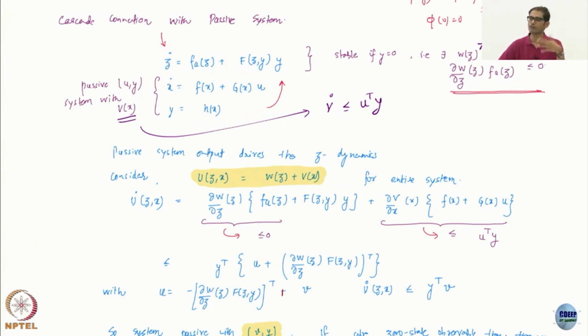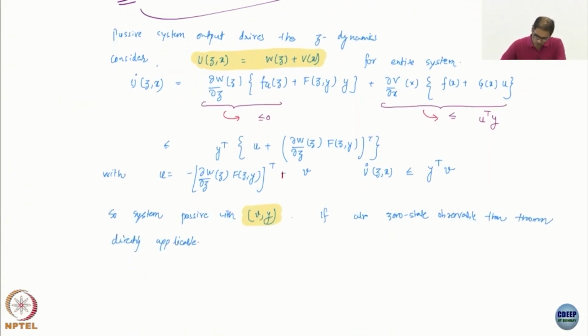And you know that once you have the passivity property and zero state observability, then you can construct a stabilizing feedback. So we have already seen this. Along with backstepping, this is a very strong method for designing controllers. So this becomes another rather powerful tool in your arsenal. We also saw these examples.